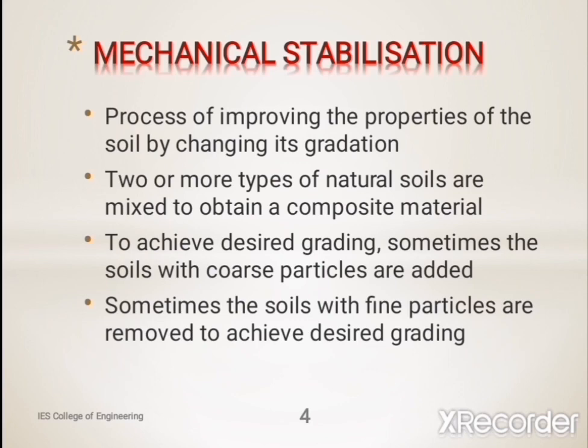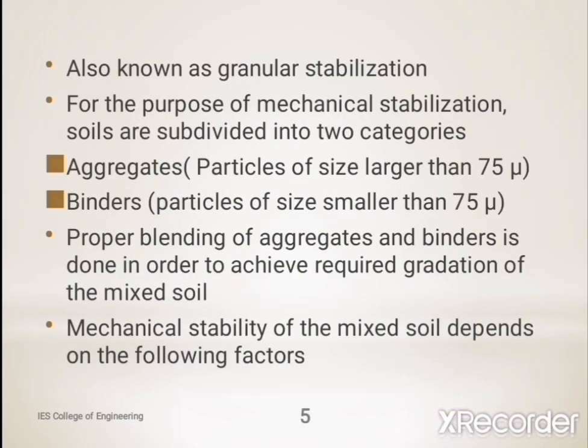To achieve desired grading, sometimes soil with coarse particles is added or soils with fine particles are removed. So coarse particles can be added or fine particles can be removed to get the desired grading. Mechanical stabilization is also known as granular stabilization.